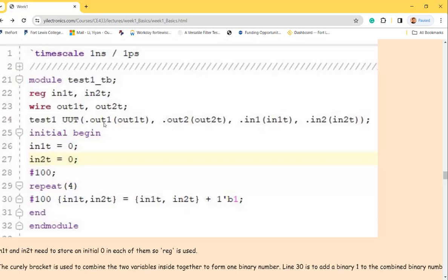And you can make individual connections of all the ports of that chip, of that module. This is your test bench. The test bench is a simulation, so that's why it doesn't have ports, because everything's within that simulator. But if you have an FPGA, if the test bench is the FPGA, you do need the ports, because the names of the ports are keywords, you cannot change them. If you are using the FPGA as a test bench, you are going to have a parenthesis, and the names of the ports in the FPGA are certain names that cannot change.